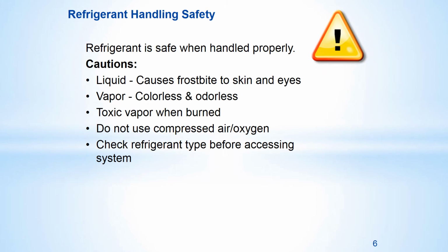Refrigerant is safe when handled properly. Cautions include: as a liquid, it will cause frostbite to the skin and the eyes. As a vapor, it is colorless and odorless and will displace oxygen in the air needed for breathing. Indiscriminate discharge of most refrigerants into the atmosphere is illegal. A toxic vapor is generated when non-flammable refrigerants are burned. Do not use compressed air or oxygen in a sealed system.